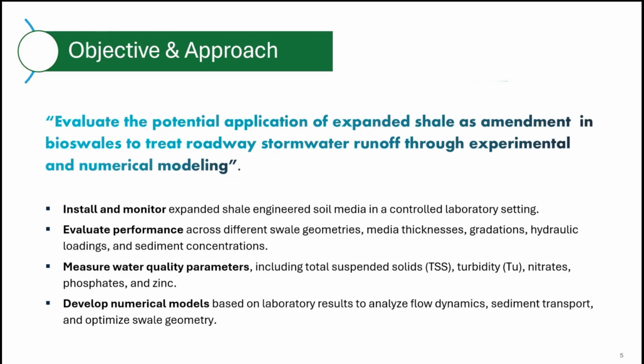The approaches we took: we installed the bioswale in the lab and monitored its performance under different conditions, including different hydraulic loading, different sediment loading, different thickness of the bioswale, and different size of the material. And then we measured the water quality at the beginning of the flume or soil, in the middle, and at the end. The water would go over the downstream as an overflow. The water seeps through the filter as underflow, and then we calculated, obviously, the efficiency of the soil under different conditions.